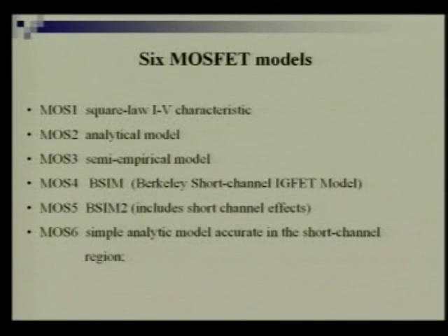Then there are 6 MOSFET models available. Similarly, BJT models are also there. MOS1 says that square law of IV characteristics. MOS2 gives you the analytical model. MOS3 gives semi-empirical model. MOS4 is the BSIM model, that's the Berkeley short channel IGFET model.